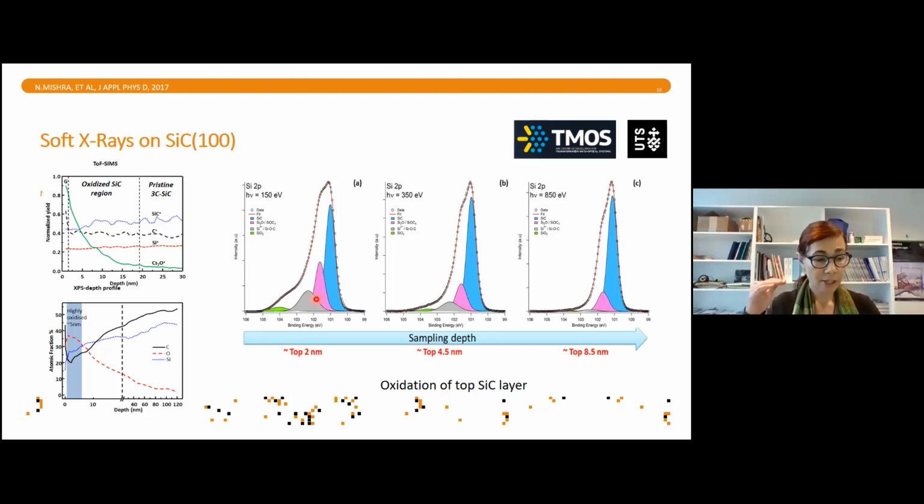And I just wanted to remind you that when we work at those 1100 degrees, another thing I forgot to mention is that 1100 degrees, which we use for the synthesis of graphene, is a temperature where the nickel, the silicides and the copper are basically in a melt. So we're actually working in liquid phase epitaxial growth.